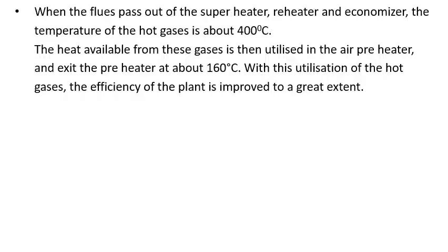If the flue gas has less sulfur, which in turn means the fuel has less sulfur, right, I can discharge at around 120 degrees centigrade. But if the sulfur content is high, I cannot. Generally, solid fuels like coal have to be discharged at around 150 to 160 degrees centigrade because of the sulfur content.